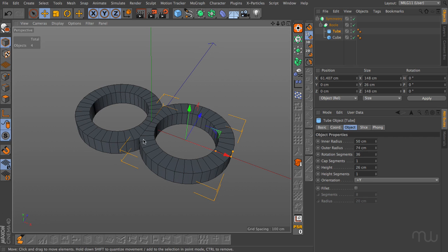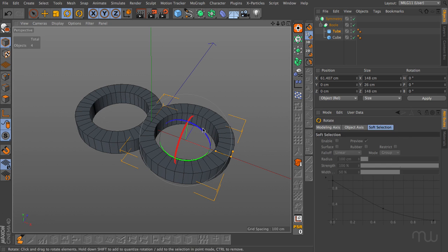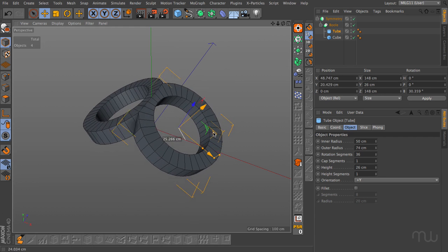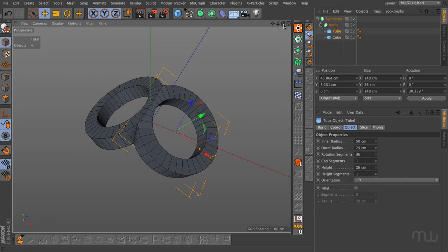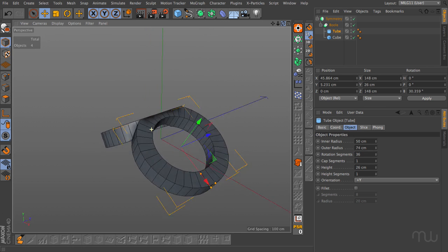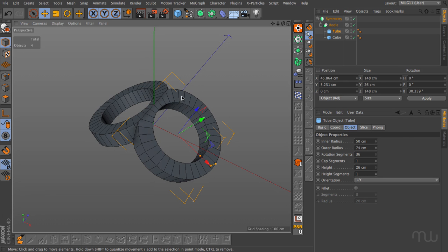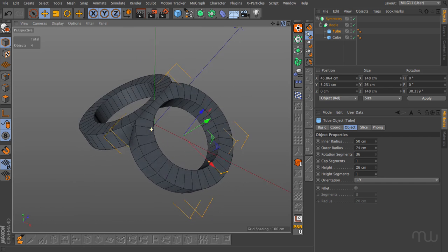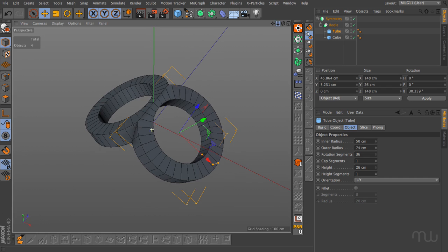Now you can do this in, I think, Max, you probably do it in most 3D applications, but the symmetry object just isn't up to this in Cinema. And you can obviously rotate, and you can get some pretty interesting shapes like this. Because the cube only has one side, the boole is very simple. You probably bounce this down to an object and then do a bit of cleanup, but it wouldn't be too severe. And this will work with really complex objects. You can come up with new shapes, but it is a hack, and until the symmetry tool can deal with this, this is the only way you can actually do this.